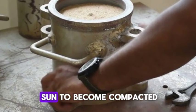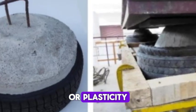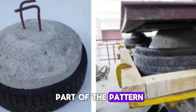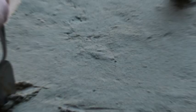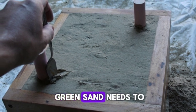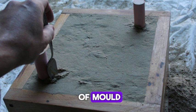5. Plasticity or flowability. The ability of the sand to become compacted and behave like a fluid is known as flowability or plasticity. When rammed, it will flow uniformly to every part of the pattern and disperse the ramming pressure uniformly in every direction. 6. Green strength. After adding water, the green sand needs to be strong and durable enough to allow for the creation and manipulation of the mold.